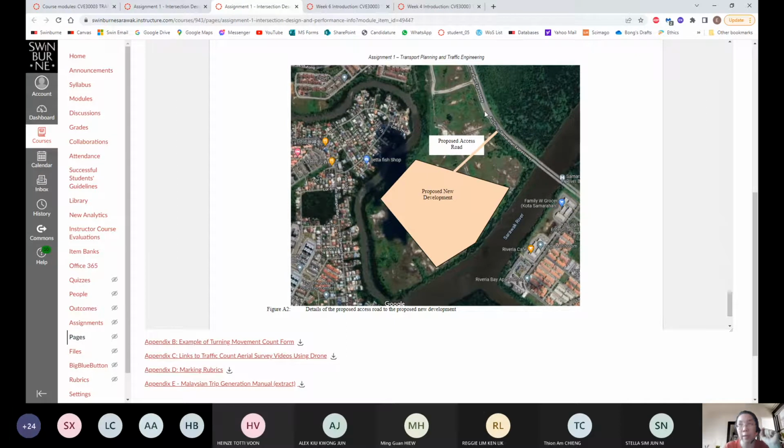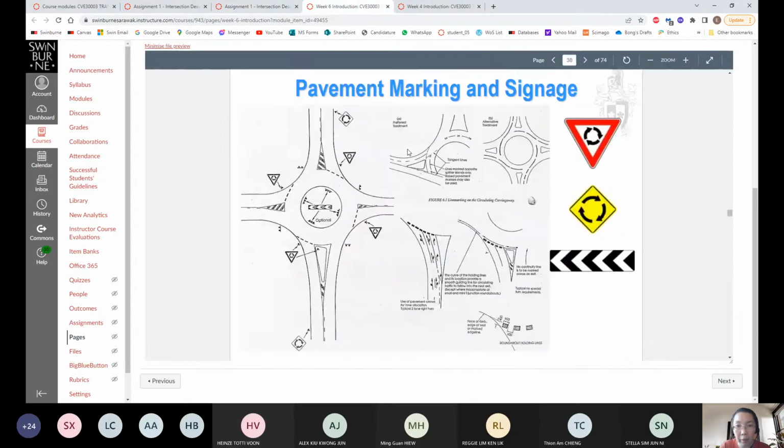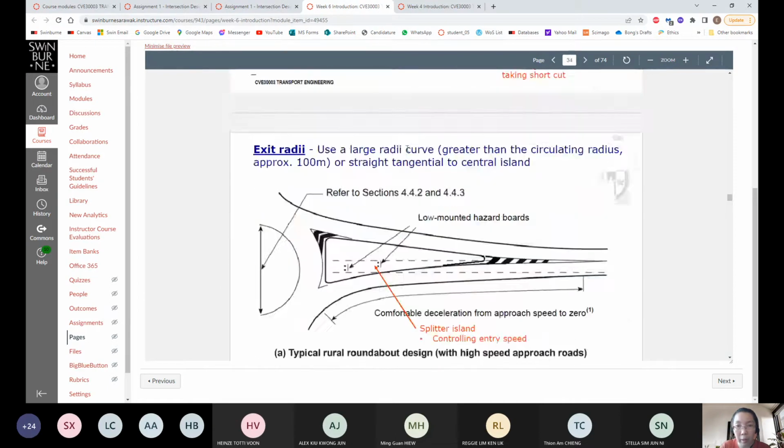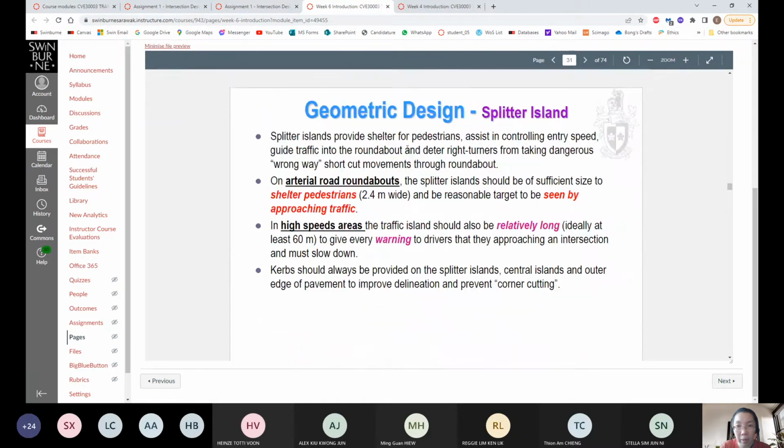if you look at your existing traffic survey from task 3, the vehicles plying this road, you would have heavy vehicles. But having said that, do you need to specifically consider heavy vehicles or not when you put in your roundabout here? This is a 4-lane two-way. So when you have a 4-lane two-way, when you put a roundabout here, it will not be too small where your heavy vehicle cannot negotiate around it. Okay, let me just scroll to that.